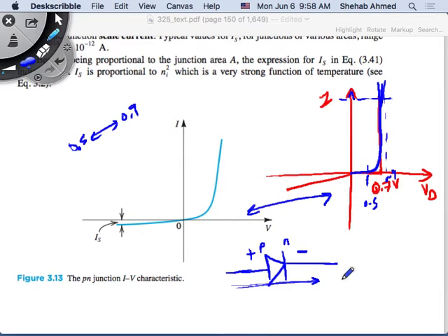Oh, so in order for it to go, there has to be a specific amount of voltage. Exactly. Yes. And that's what we've been doing. That's what I've been talking about, right? It's the barrier. You had a barrier. This barrier, you have to decrease the barrier by creating a forward bias condition. How do you create the forward bias condition? By adding an external source that puts a positive voltage here versus this node in the circuit. If you do that, you decrease the barrier voltage, allow diffusion to happen.